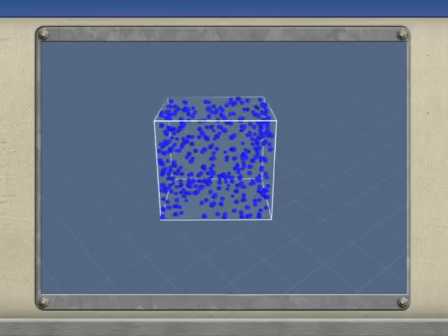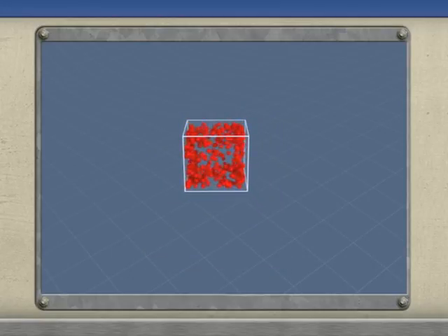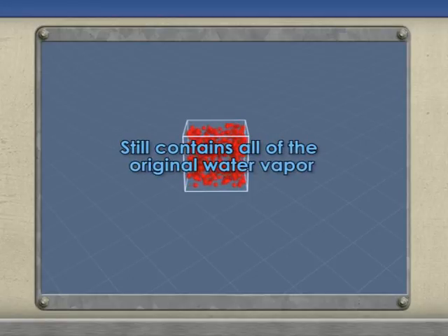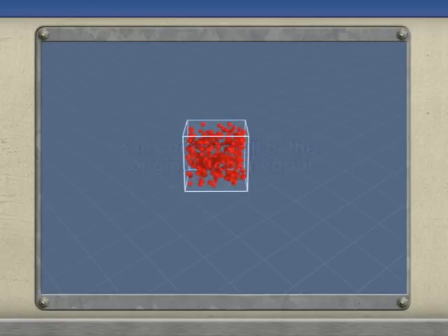As ambient air is compressed, its moisture concentration and dew point increase. Air compressed to 100 psi occupies about 1/8 of its original volume, but it still contains all of the original water vapor. If this air was sent directly out into the site and was then returned to the ambient temperature, a considerable amount of liquid water would drop out.